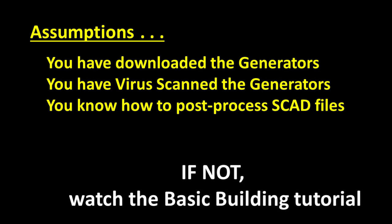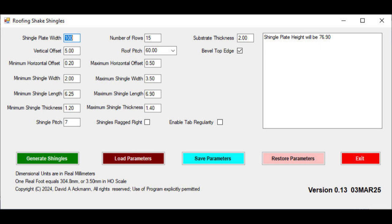As a reminder, the default values of all parameters represent good starting values, and if you are new to a generator, I recommend starting out by just clicking on the green Generate button to see how things work. The green button will ask you for a location to store the SCAD file, which contains 3D instructions to create your desired object. And to terminate the generator, just click on the red Exit button. The maroon and blue buttons load and save the configuration parameters respectively, and the orange button restores the default values.